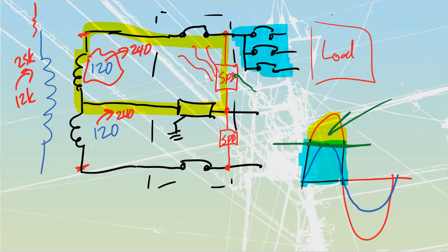Avalanche diodes are another type. It is a type of Zener diode. They do conduct at a reverse bias voltage level. So like a regular diode, you can forward bias and you can reverse bias them as well. But they can tolerate massive amounts of let-through, more so than a Zener. A Zener is regulated. It's got just a max amount of current. These other ones are designed to have surge current go through.